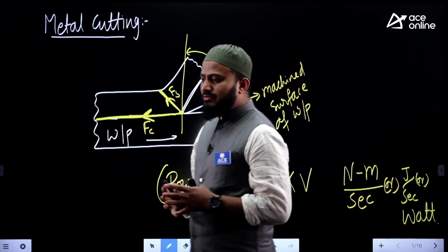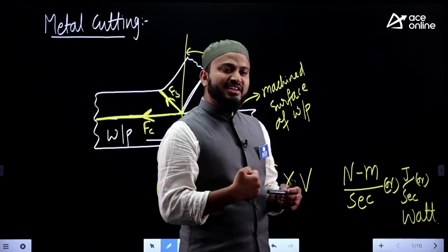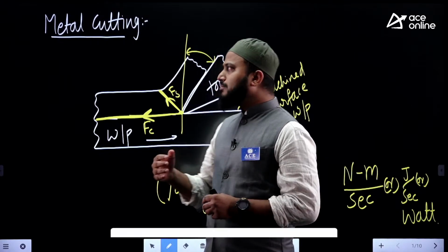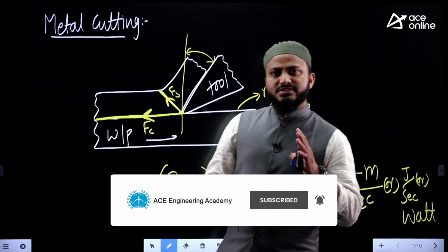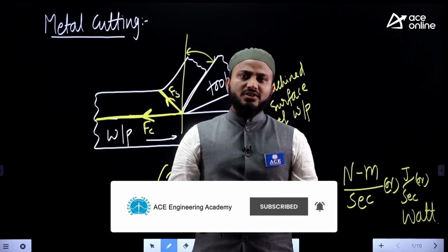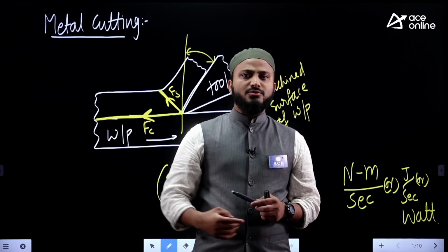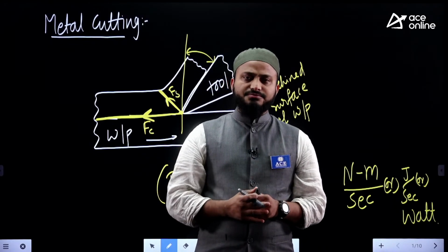With a minimum power consumption condition, we create the tool geometry so that it applies in any kind of conventional machining operation, not only plain turning. Many people feel that this figure came out of plain turning. No, even if it is a single point or multi-point cutting tool, in every machining operation you can go on the orthogonal plane and project the same view of the tool and workpiece.